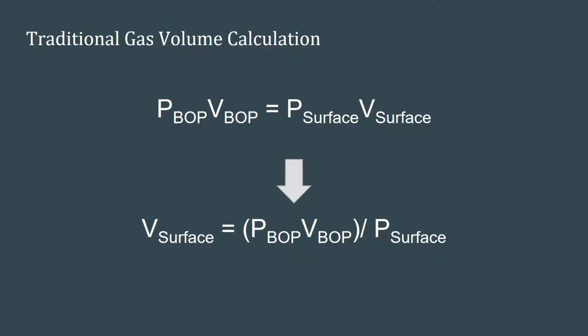Today's well control training uses Boyle's law to model gas expansion. If a kick's initial volume is known, Boyle's law is used to calculate what volume the kick will be at the surface. This procedure was what we used in our 4060 well control lab.